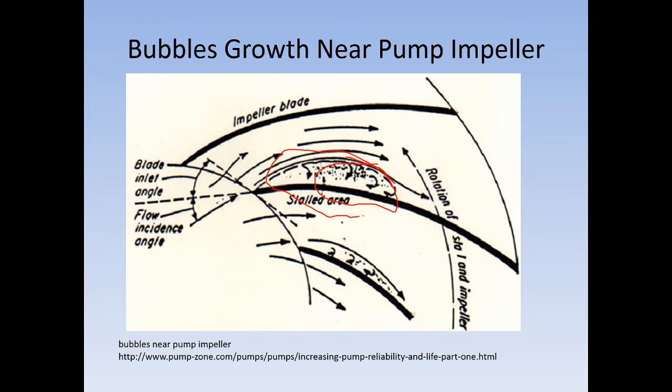Time by time the impeller will be damaged, and some part of it is removed by this repeated hitting, and finally imbalance creates vibration and so on.